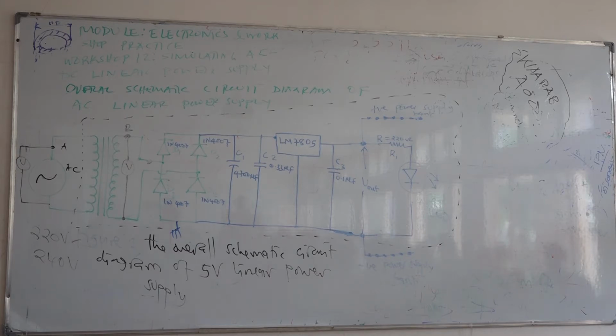So measuring the output root mean square voltage from the step down transformer is very important, because sometimes you might feed it 220 volt. If you don't change some parameters, especially the primary inductance and secondary inductance of the transformer, then you feed 220 volt and at the output you receive 220 volt, which is wrong, because the transformer did not do anything. We'll see it in the simulation part. In the hardware implementation, or practical part, we don't have that challenge.